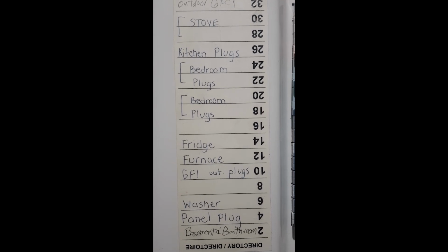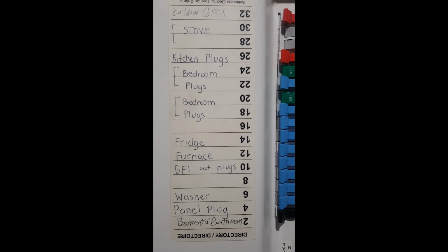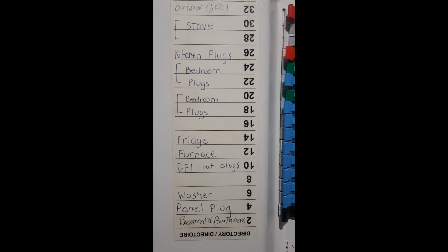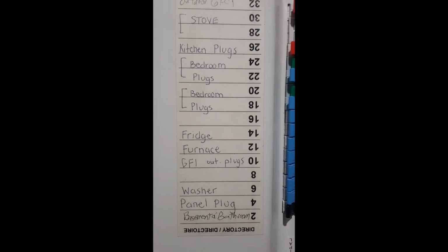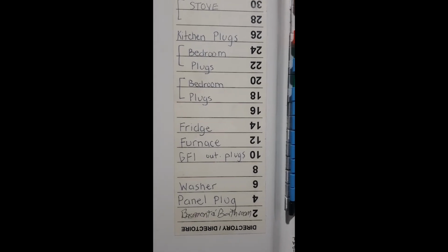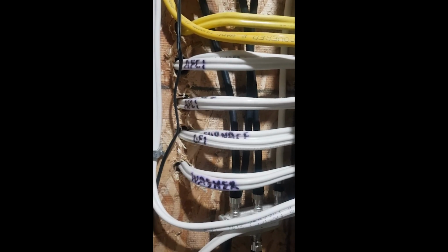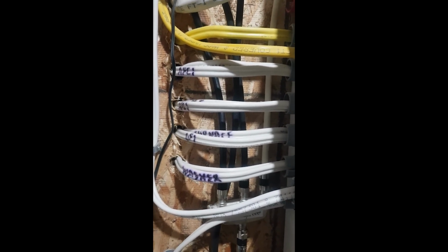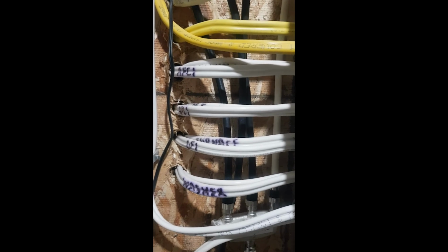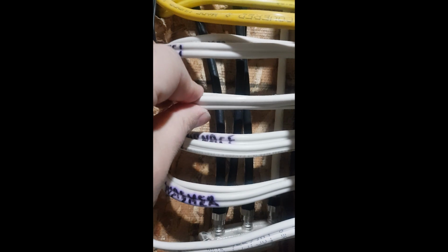Now, most of the time, those sockets don't have anything connected to them. And the designer assumed that you will not use all of them at the same time. But if you do so, and you connect large loads at the same time, like a hair dryer, an iron, a vacuum, all at the same time, what will happen? You will be consuming a lot of current from that specific circuit, which will lead to an overload, an overheating in the cable. To protect the cable from being overheated and leading to melting of the PVC or plastic material, this will trip.